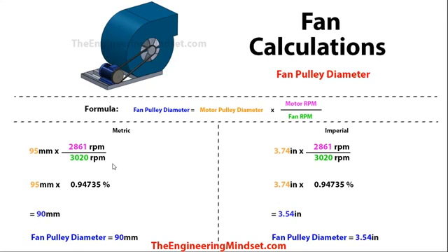If you haven't already purchased the equipment, then you can look it up online and see what the RPM is going to be for these fans and motors. For the fan, that's going to be the RPM you need to provide X amount of ventilation or airflow rate, and for the motor, this is the RPM that it's going to rotate at.